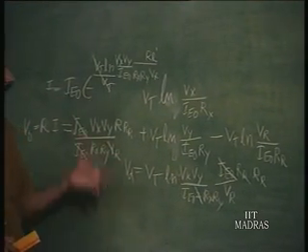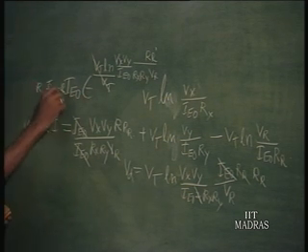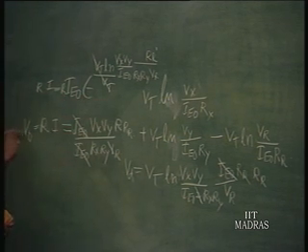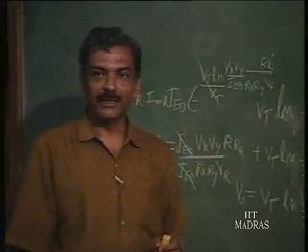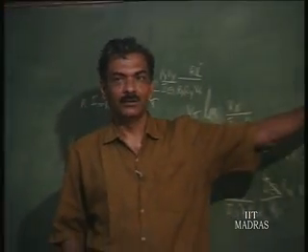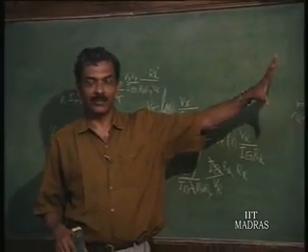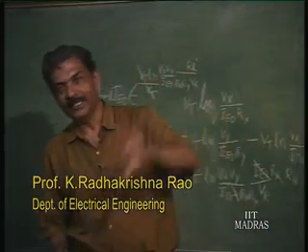That becomes the effective diode voltage, and then it is to be multiplied by R if we take the anti-log, and the output voltage will be totally independent of the effect of Vt and IE naught. So, when we design a multiplier, we do not have to do any compensation, it is automatically getting compensated, because you are taking log and taking anti-log.